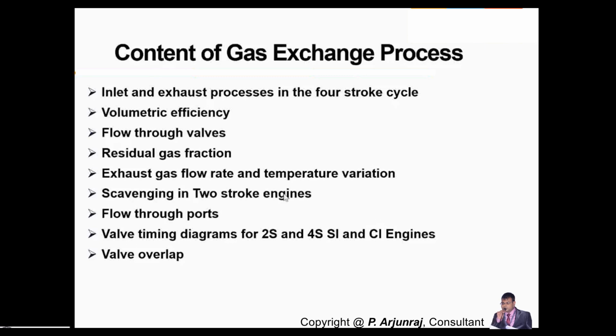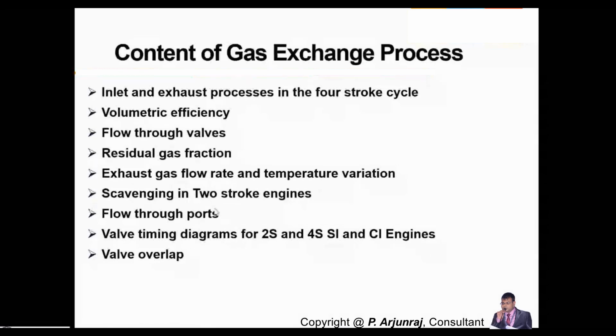And in the case of a two-stroke engine, you don't have valves. Okay, you have only ports. You have the inlet port, the transfer port, and the last one is the exhaust port. The inlet port will allow the air in the case of a diesel engine, and the air-fuel mixture in the case of a gasoline engine.